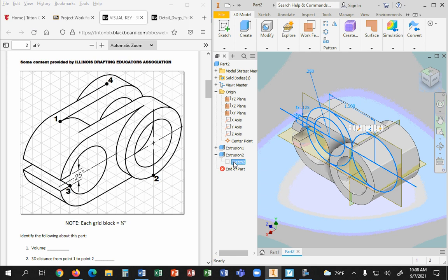Because I didn't pick the face of that circle to make it. I used center extrude. So everything's being extruded from the center, and that's okay. That's the only reason this worked. Yes? No? Not yet. Now the last thing to figure out is the cut inside, correct?